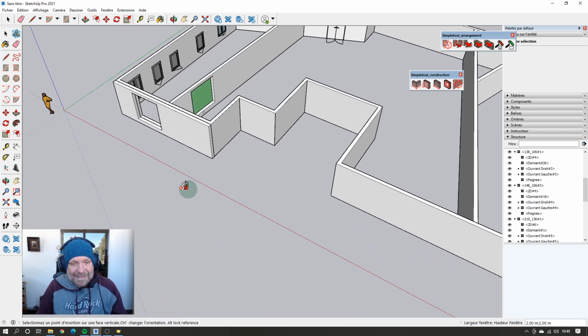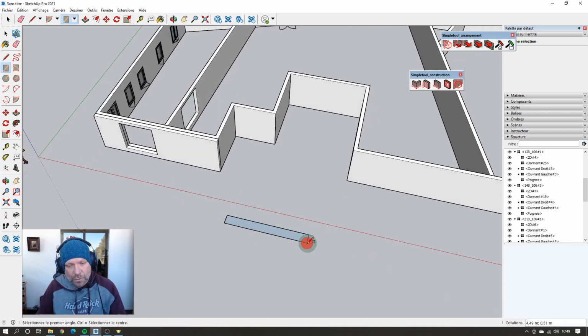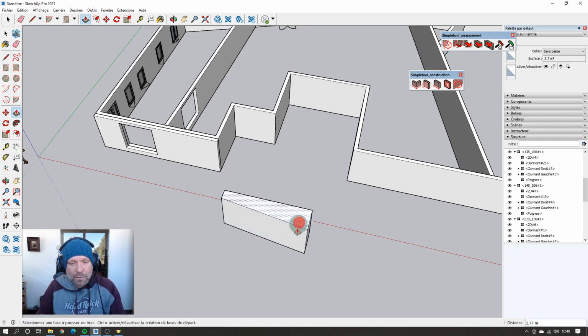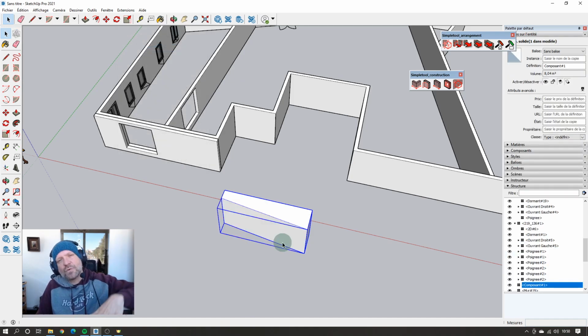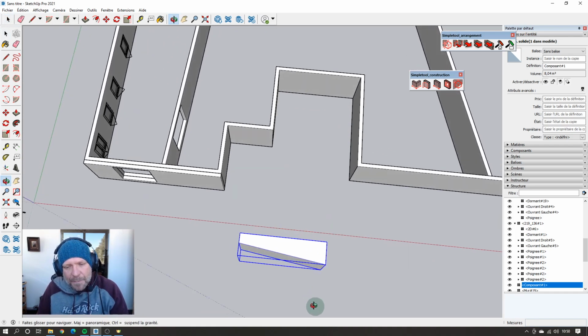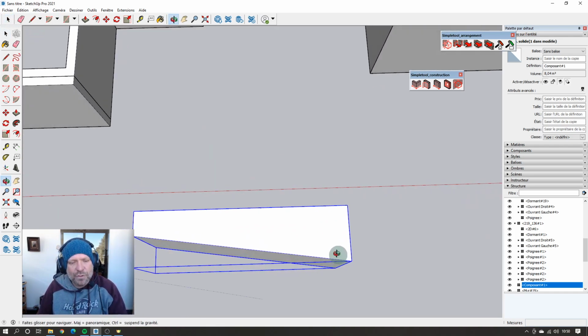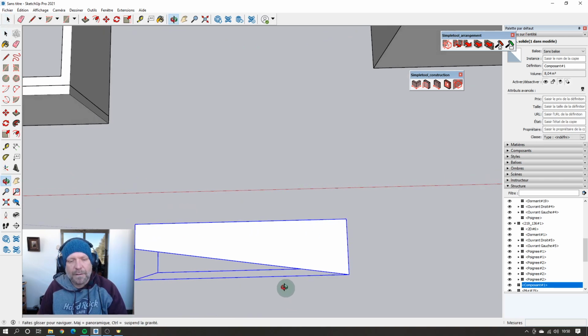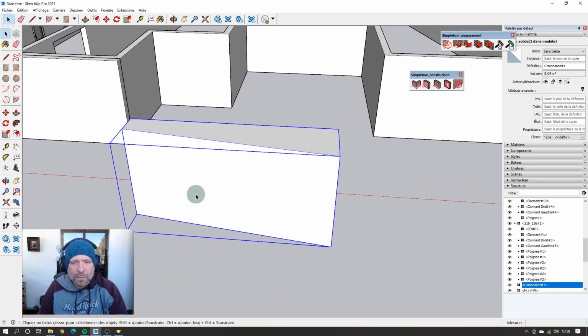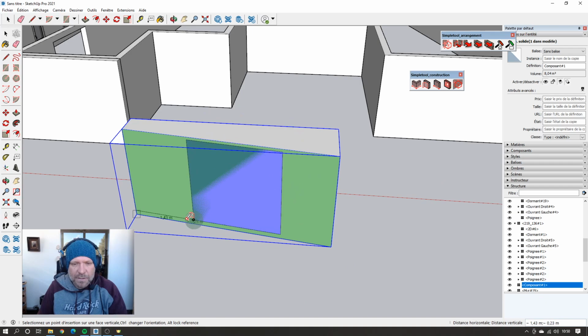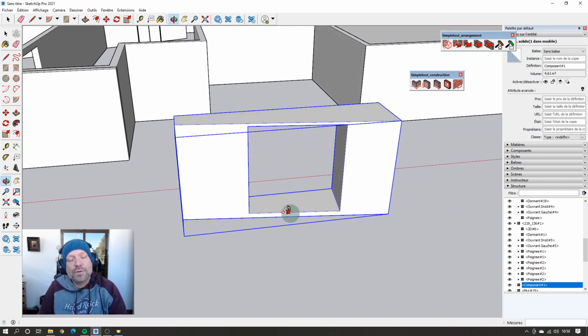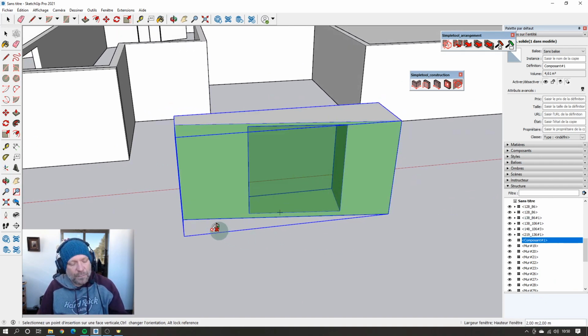So this tool could be used on all vertical shapes. For example, if you import a DWG, sometimes you want to push up all the walls at one time, but on the DWG, walls are not aligned. So here with a simple opening, you can make the opening, whereas if you want to push-pull the face after that, it will not work